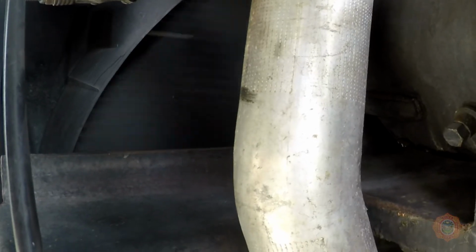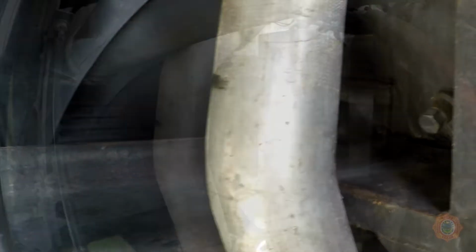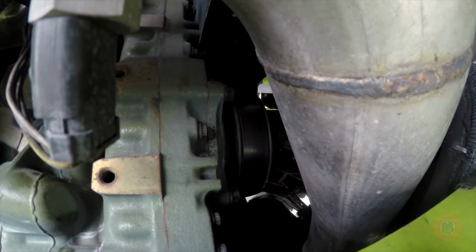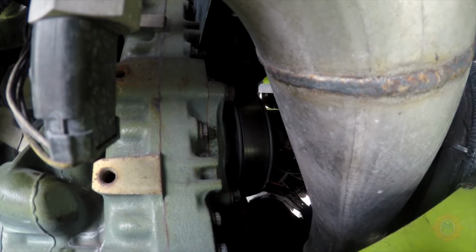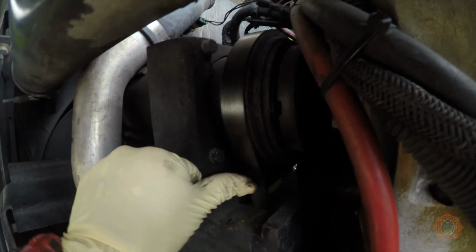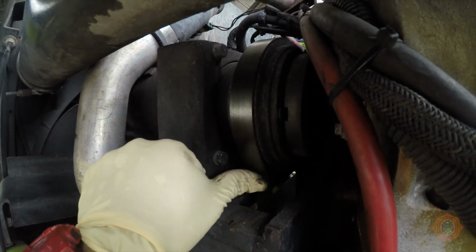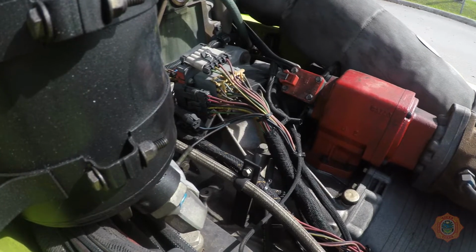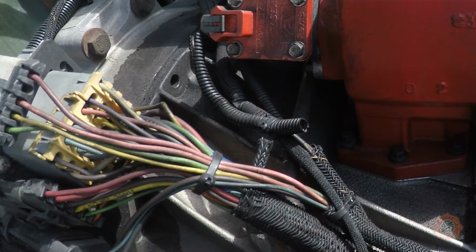Some engine cooling fans activate automatically without warning. Use caution when working near the fan. Never attempt to check the belts while the vehicle's engine is running. Check all engine compartment belts for tightness and excessive wear. Look for frayed, cracked, loose, or otherwise worn wiring. Refer any wiring problems to a mechanic for correction.